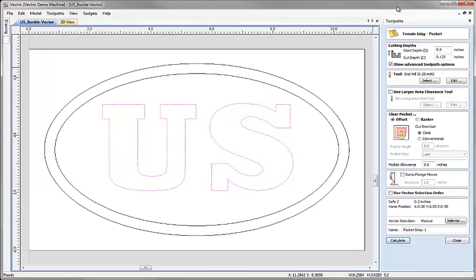If we think about the fact that the tool we're using is round, and when it cuts something out, the external corners will be cut correctly, but the internal corners will always have the roundness of the tool on them. So when we're doing an inlay, both the pocket that the inlaid part is going to go into and the part itself need to have their corners rounded off. For the pocket where the part's going to be inlaid into, it needs to have its internal corners rounded.